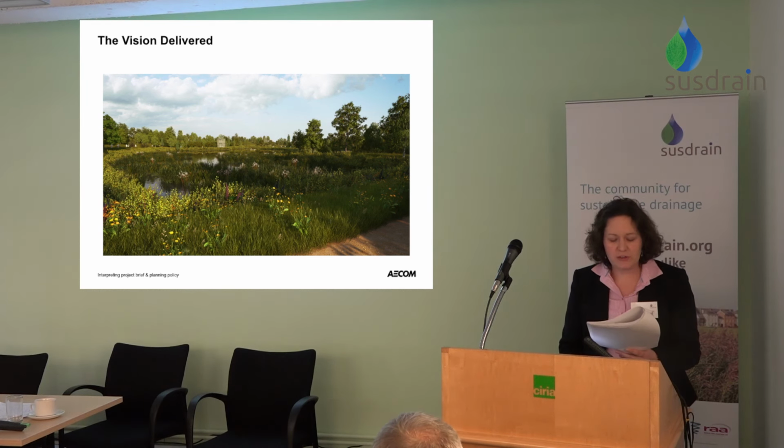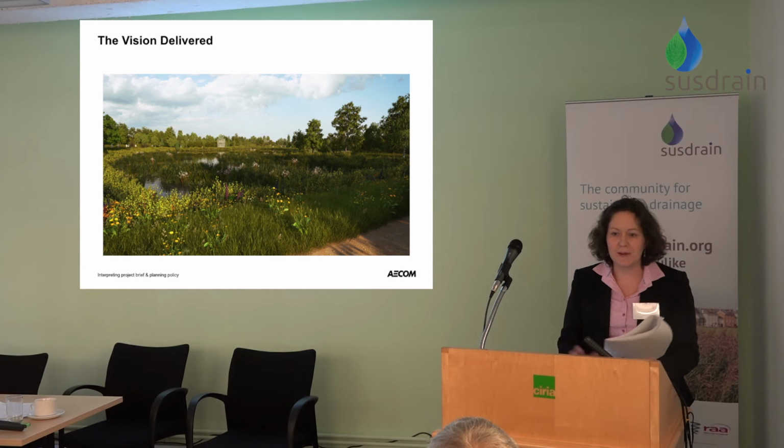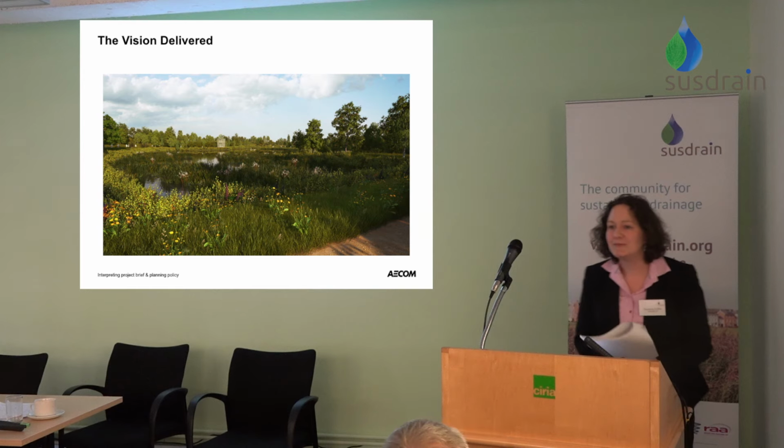At the beginning of my presentation, I mentioned some of the policy relating to the development. Some of the key tasks were to design the surface SUD systems to reduce runoff volumes, to control the rate of flow and improve water quality, and to include water conservation measures to reduce potable water consumption. This image shows how the project brief and planning policy will look in 15 years' time, once the planting's established, when those are delivered. Thank you.